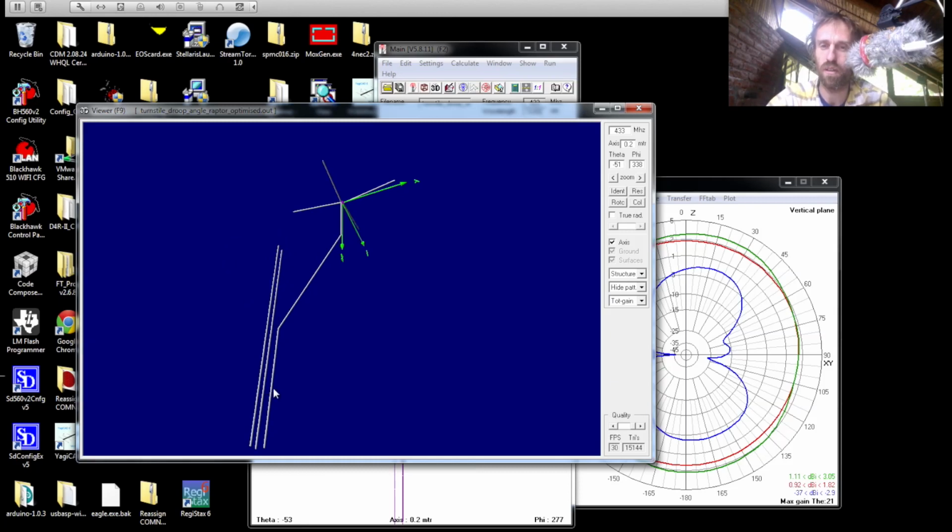So that's really important. And that's why if you're putting this antenna on a multi-rotor and you want to get maximum performance, you'd want to stick it out on one of the arms, like out the back of the multi-rotor, so it's well away from all the metal wires that connect the motors and the ESCs and all that sort of stuff, because that will affect your radiation patterns. And let's just turn on the radiation pattern here.